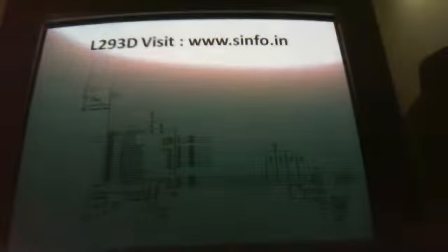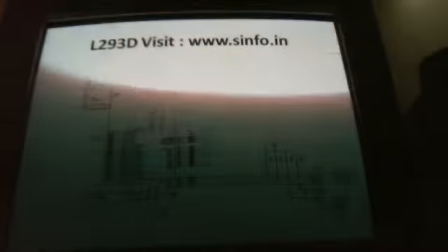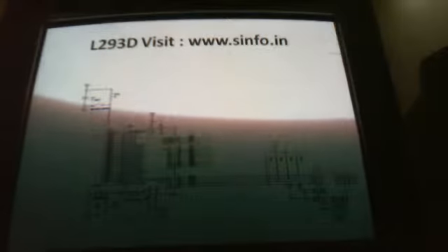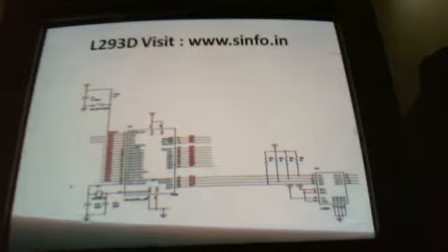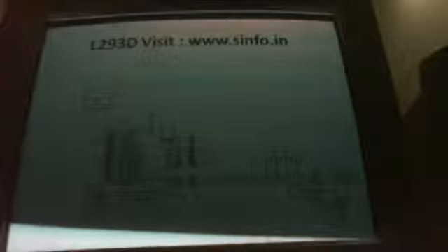In the next diagram, the PIC 16F877A's IO ports are connected to the inputs of the L293 driver IC. Pin number 1 is reset, MCLR, connected to a 4.7K resistor and at the same time to a reset switch. Pins number 13 and 14 are connected to a crystal oscillator. You can use any crystal oscillator from 4 MHz, 10 MHz, 16 MHz, 20 MHz. PIC pins number 11 and 32 are positive, and 12 and 31 are ground.